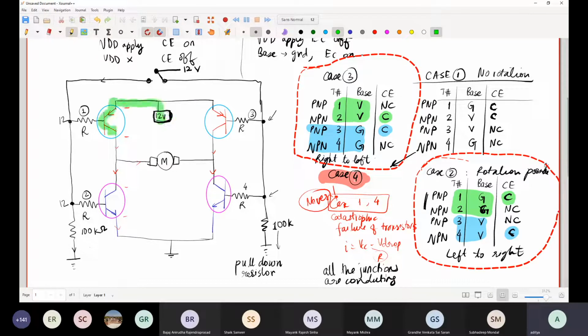going to this, then, oh, wrong path. 12 volts going to this, going to this, going to this and this. So just by the flick of a switch, one is able to reverse the direction without having to change the entire wiring. And this is convenient because when you want to switch the direction of the motor, you do not want to remove the connections at all times. That is just dumb. Of course, if you just want to test something out, you can do it. But once it goes into a complex apparatus, you really don't want to do this time and again.